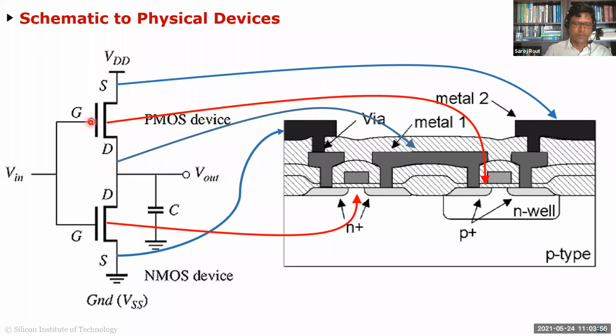You put a smiley face, you put a sad face, you put anything here, as long as the mathematical model is defined between these three terminals, actually four terminals, there's a bulk here too, you'll see the same thing. It's just a mathematical model, right? But when you send this to the foundry house to fabricate it, they'll send you back and say, what is this? I don't understand what this is. Because all they understand is those layouts, which get converted to this.